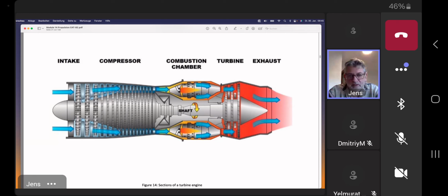APUs, for example, depending on the engine type and what the task of the engine is, we find mainly axial compressors. In some engines designed for helicopters, we have a combination of first an axial compressor followed by a radial compressor. This makes the engine consume more air, but you still save a lot of space. So, generally, there are 3 normal kinds of compressors: radial, axial, and the third version would be a combination of both. Please bear in mind the advantages and disadvantages.